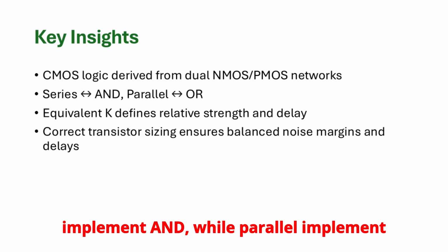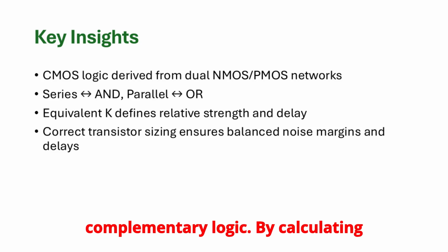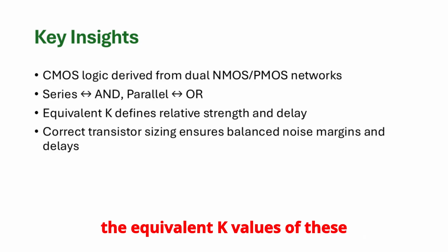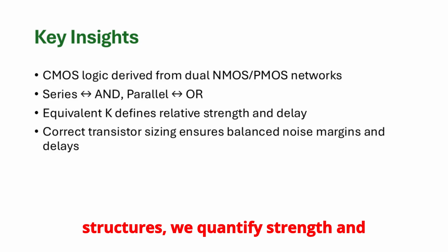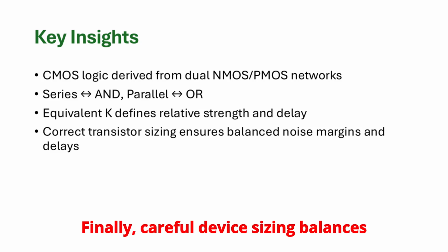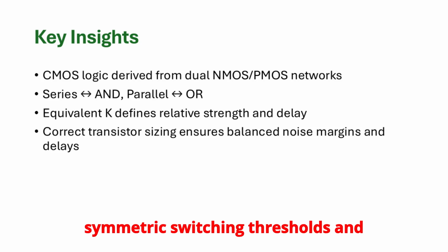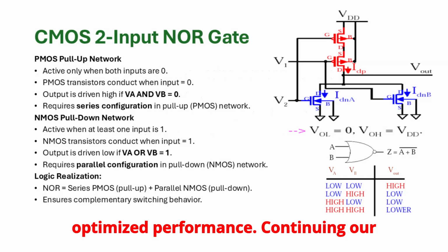Series connections implement AND, while parallel implement OR, but NMOS and PMOS follow complementary logic. By calculating the equivalent K values of these structures, we quantify strength and predict delay characteristics. Finally, careful device sizing balances pull-up and pull-down strengths, ensuring symmetric switching thresholds and optimized performance.